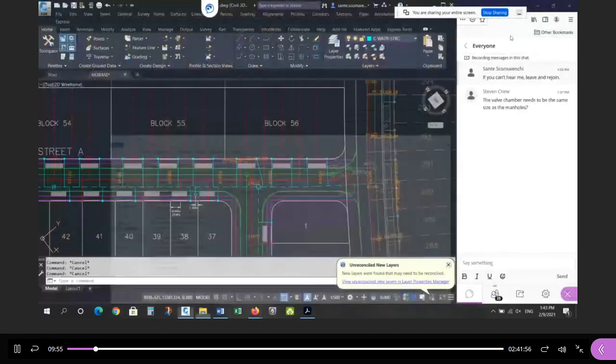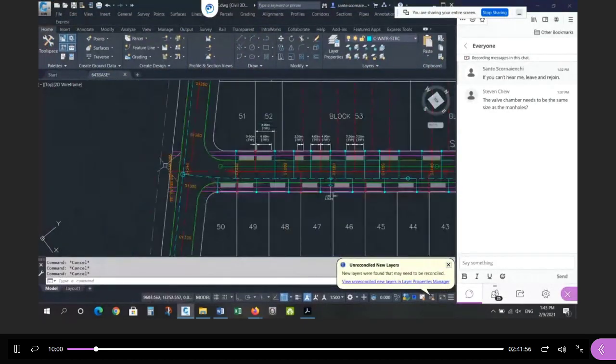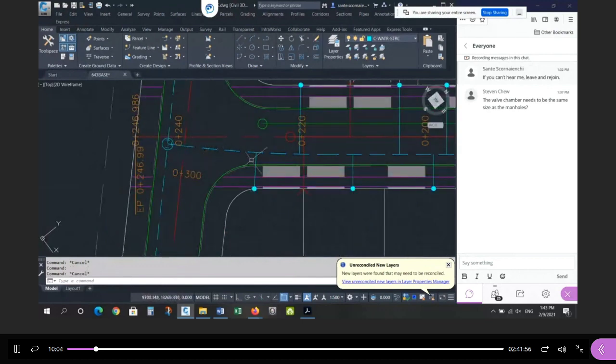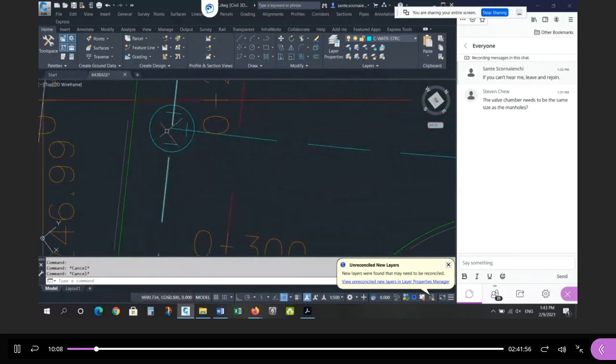All right. A couple of other things. So I used the round one here and the round one here. I didn't put my labels, but you had to have labels on this. Another thing here, this pipe had to connect to this pipe at 90 degrees. I wasn't going to use joint deflection on a T. I want this to be nice and clean. So this line versus this line is exactly 90 degrees so that I can use this T.